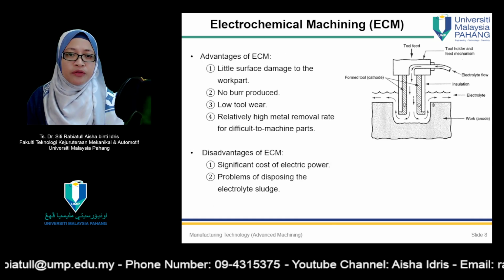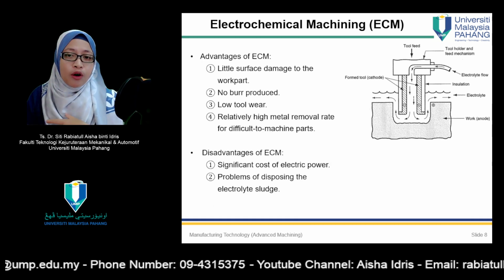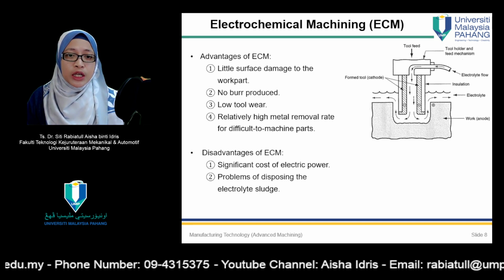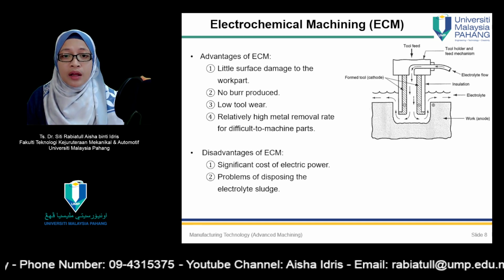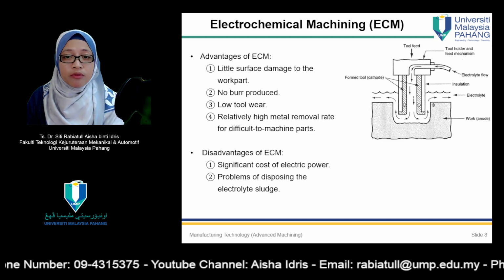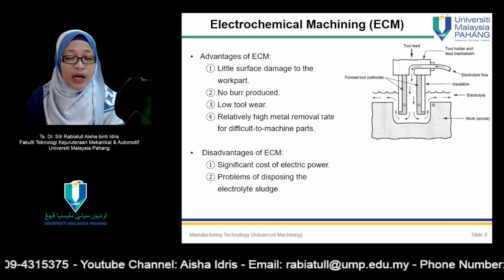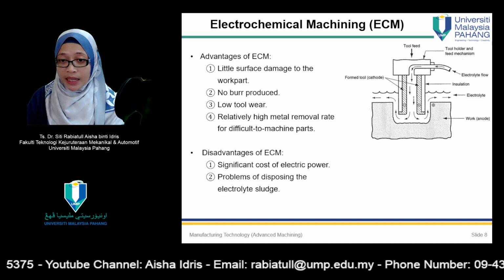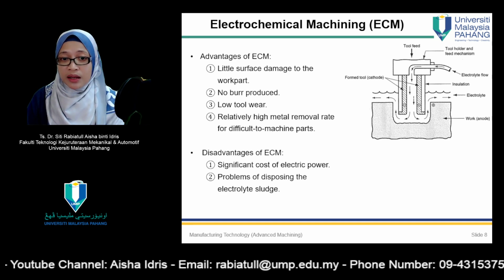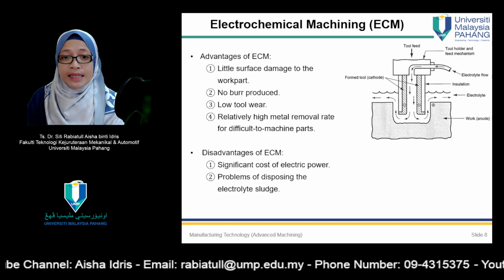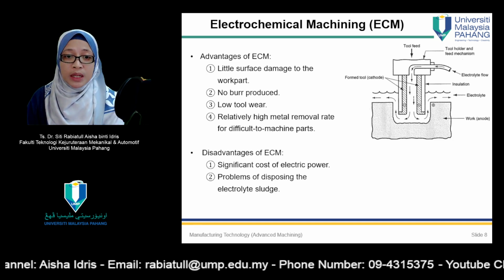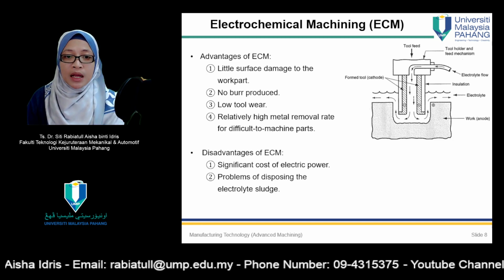Large amounts of electrical power are required to perform ECM. As the equation indicates, rate of metal removal is determined by electrical power, specifically the current density that can be supplied to the operation. The voltage in ECM is kept relatively low to minimize arcing across the gap.